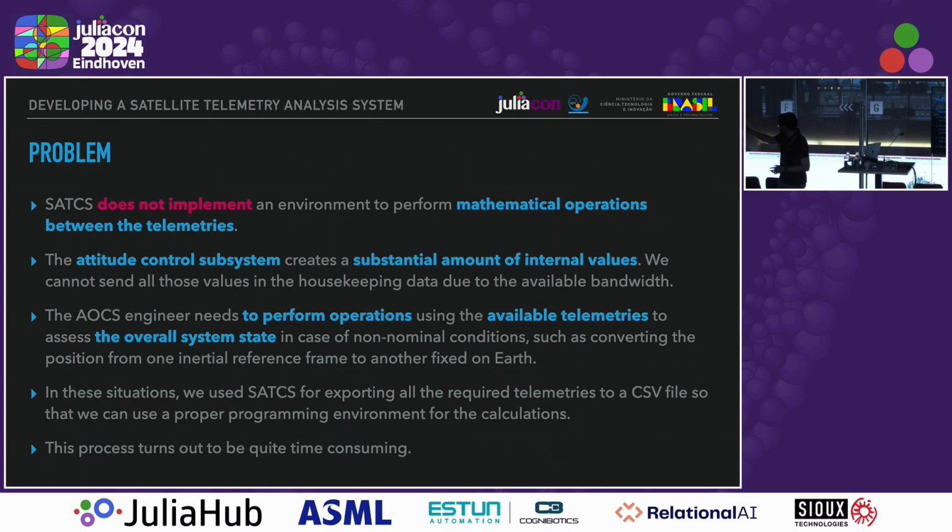So we have to keep this information as small as possible, but then we have to reconstruct that information by performing operations with those telemetries to verify if everything in the satellite regarding the attitude control subsystem is working correctly. So before, what we did was use SATCS to export a CSV file, load the CSV file, and do this computation, but it was very time-consuming.